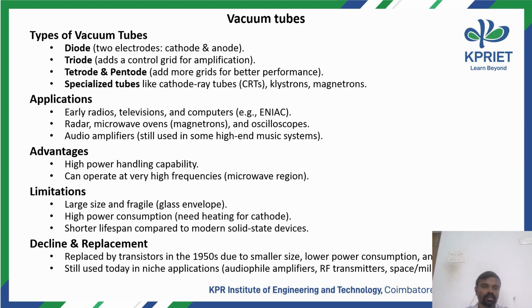The limitations: the main limitation is large size and fragility. Since we are using a number of vacuum tubes based on the applications, their size could be very large. And since the vacuum environment is to be surrounded by a glass envelope, they are very fragile. So that is one kind of limitation. Then they consume very high power, because of their physical property: the cathode needs to be heated to emit the electrons. In such cases, high power consumption happens.